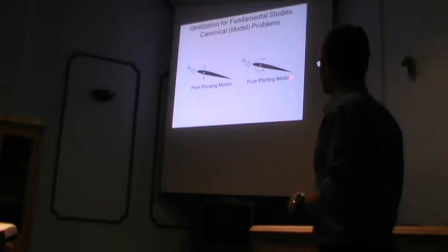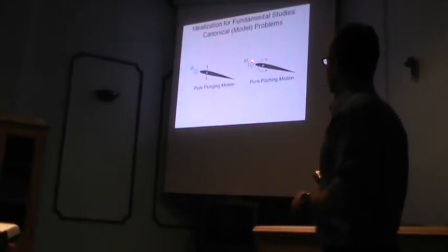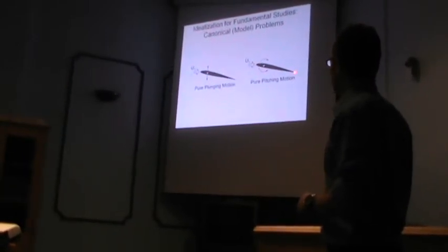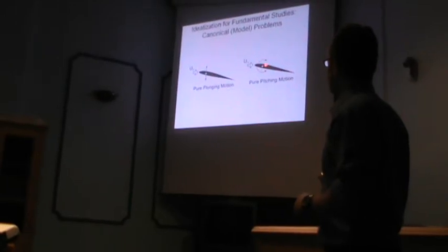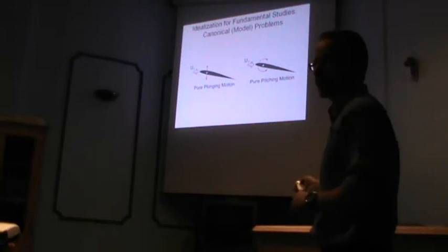One thing I want you to note, because unfortunately, I don't have it anywhere in these slides, is the definition of the angle of attack: if you connect the leading and trailing edge of the wing, then the angle between the free stream and this chord line is what I call alpha, or the angle of attack.